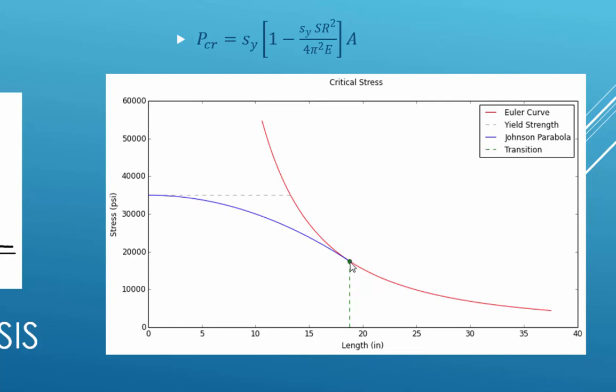This spot here, the transition point, this is where the column constant is equal to the slenderness ratio. So we have the Euler curve coming up to this point, and then material factors start making more of an impact, and we end up finally at this point, and this point is where the failure stress is our compressive yield stress, just force over area.